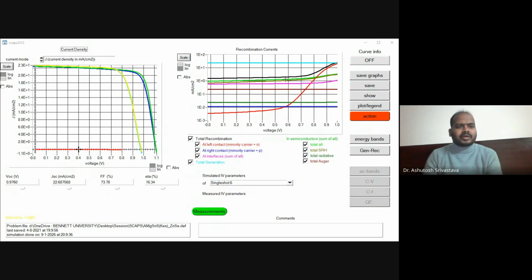Okay, the same. If you can see here, my IV characteristic is lying in the first quadrant. But as a student or as a reader, if you remember, the solar cell quadrant is always the fourth quadrant. So we convert it this way.